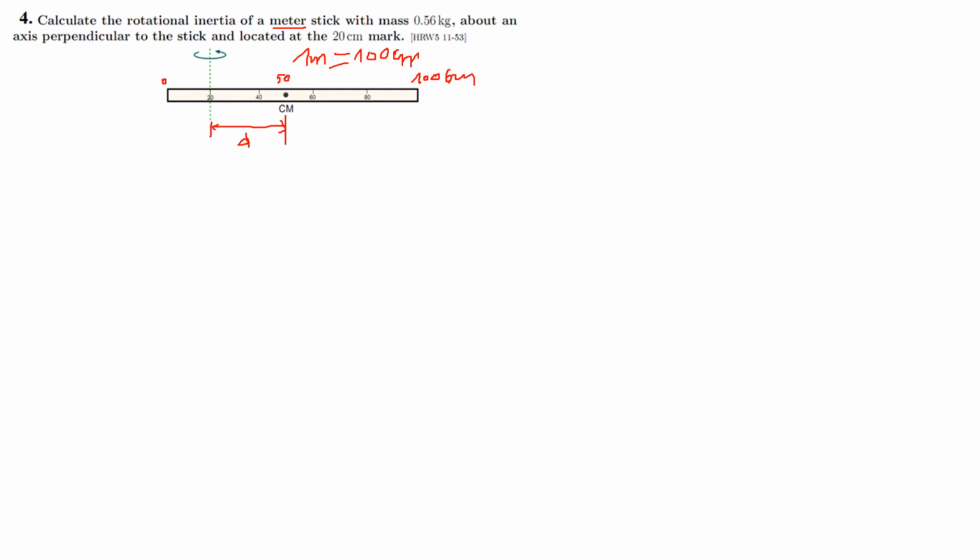And here comes a fundamental principle which is called the parallel axis theorem. The parallel axis theorem states that if we have a point P here, there is a moment of inertia about point P and a moment of inertia about the center of mass.